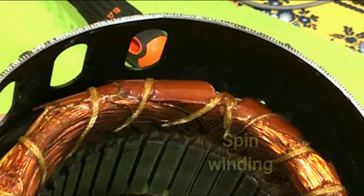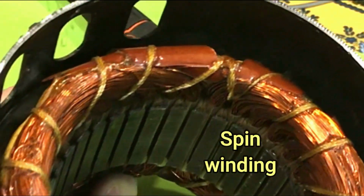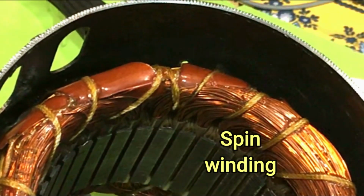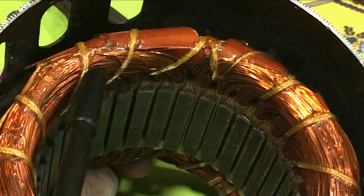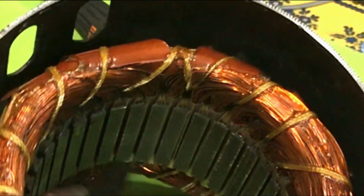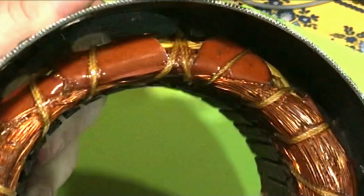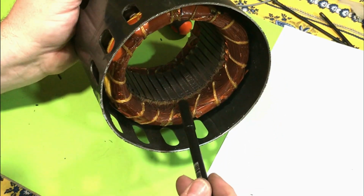If we open the motor and look into the stator, it's easy to find the spin winding because it's just a two-pole spin winding to have the highest possible speed, that is in this case 3600 RPMs in 60 Hertz.